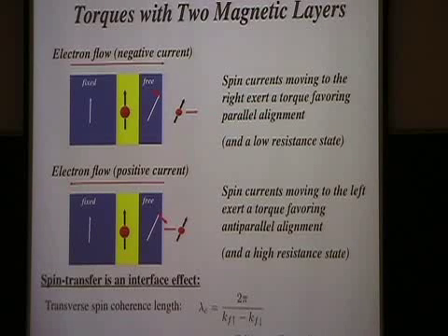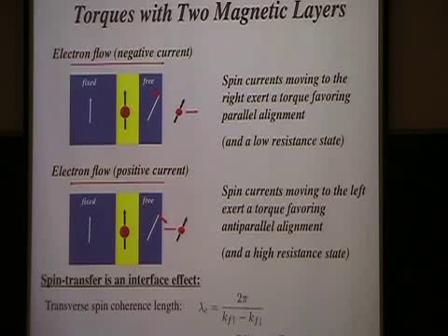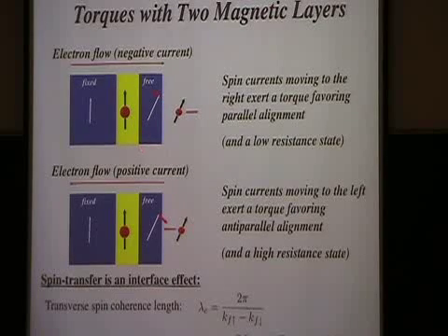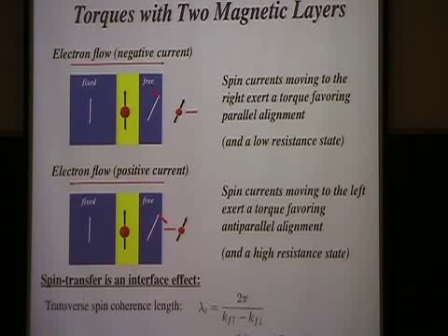Also, there will be some relaxation within the non-magnetic layer. That's right. There's also spin relaxation in the non-magnetic layer. Spin-flip scattering also reduces this effect. So this layer usually should be smaller than the spin diffusion length to maintain the spin polarization in that layer. In this case, the interaction is mainly the exchange interaction between itinerant electrons and background magnetization.